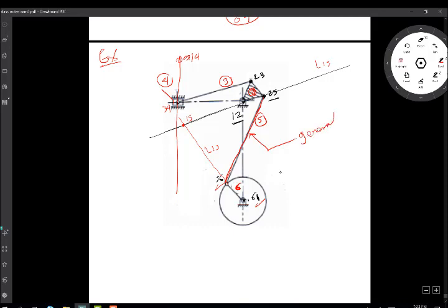So normally when I have both ends move, it will do general motion. Like link number 2 does rotational motion because it has a fixed pivot. Link number 6, the pure rotation motion. Link number 4 is pure translation. But link number 5 does a complex form of motion which combines both translation and rotation. And those are the links with both ends move.